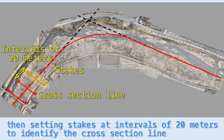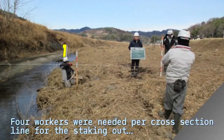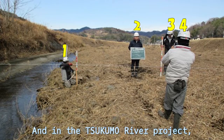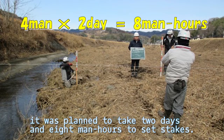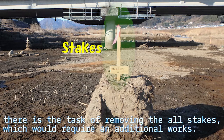In conventional works, a center line is defined at first, then stakes are set at intervals of 20 meters to identify the cross-section line that is set perpendicular from the center line. 4 workers were needed per cross-section line for the staking out, and in the Tsukumo River project, it was planned to take 2 days and 8 man-hours to set stakes.